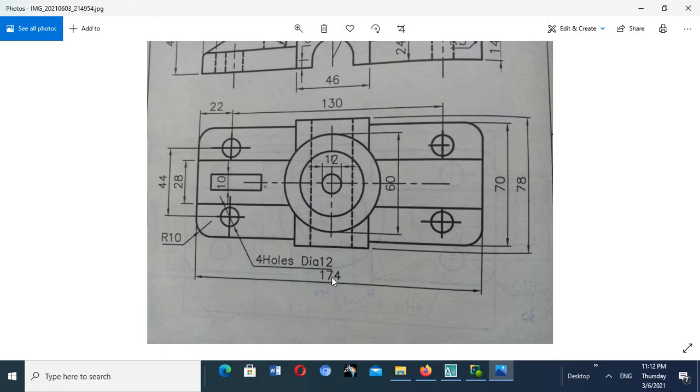Then check, the interesting thing about CAD is we save time because of productivity tools. Only I want you to watch when you are going to be drawing these circles. That circle, that circle, that circle, that circle. I will only draw one circle. This circle I won't draw, I will just mirror it. All this I will just use the mirror command. That's how efficient computer-aided drafting is.